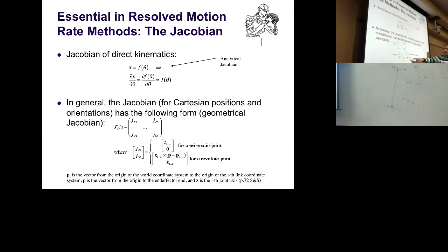So what I basically just showed you is how to compute the part of the Jacobian for a revolute joint for the position component. So I computed these three things for, let's call it, joint number 2. And for the orientation, it is just the rotation axis that you have to put in here. Okay? So that actually becomes a very easy recipe how to create a Jacobian without doing massive differentiation at all.